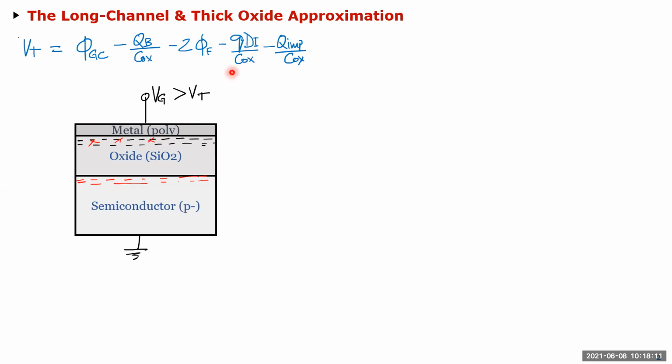And then, if you remember, when we use this equation, we found out that we actually got a depletion mode device, in other words, the channel is formed even when the gate voltage is equal to 0. And for an N-type device, we want to turn the channel on when the gate voltage is greater than the threshold voltage. So we actually artificially implanted some ions here to make that gate voltage greater than 0.